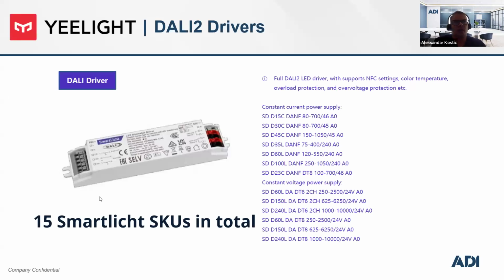So we have here a list of available DALI ballasts. We have like 15 different SmartLight SKUs in total. The main difference between DALI ballasts is in the type of the power supply they provide. So we differentiate constant current and constant voltage power supply. Do we use one or the other? It depends on the type of the light which we connect to the DALI ballast.